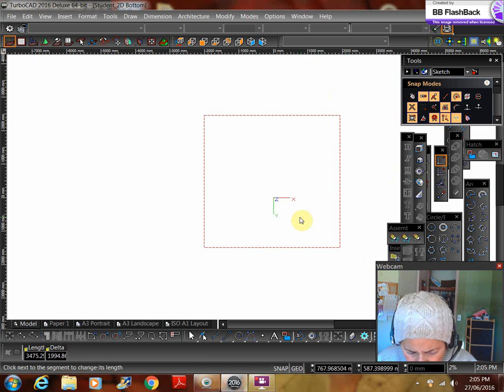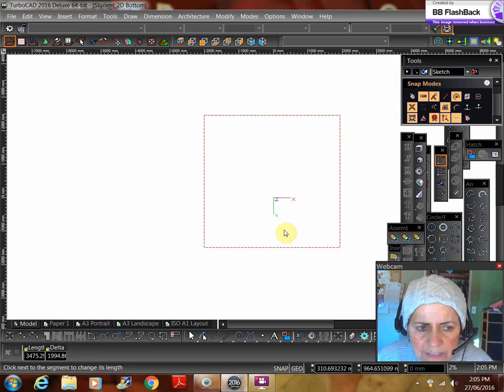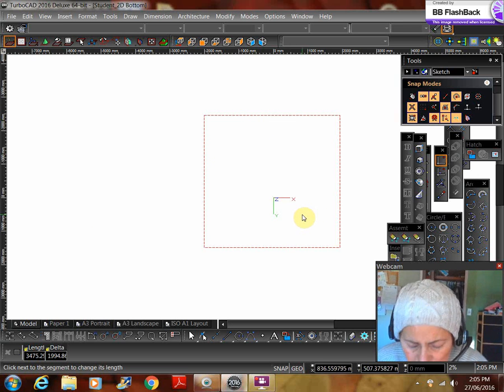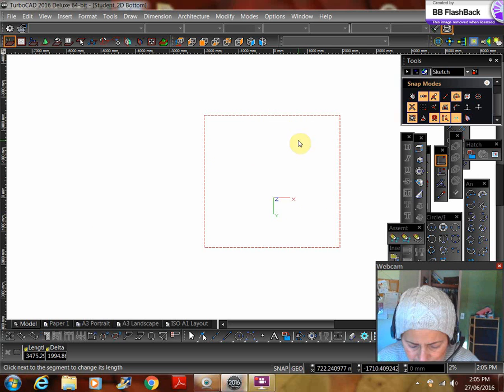See this, if you use this one, a student 2D template that I'm using now, it has the user coordinate system ticked. Therefore, it is correct. It says the icon of the user coordinate system aligns itself to the current work plane. Means this x-axis is parallel to this, and this y-axis is parallel to this. So this is a work plane, and the coordinate system, that is the user coordinate system, is parallel to these ones.